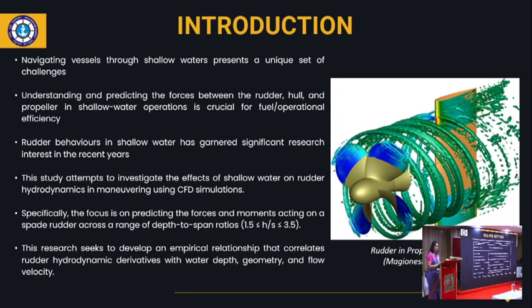And the computational facility we have at the campus, we used that is a 32 core 256 GB RAM system with two licenses of the Shipflow solver with 16 core permissible limit to each. So we had an overall of 13 depth cases, and each case had to be run for 7 different angles. So we had a total of 91 simulations to run for this simple study, or the introductory study.